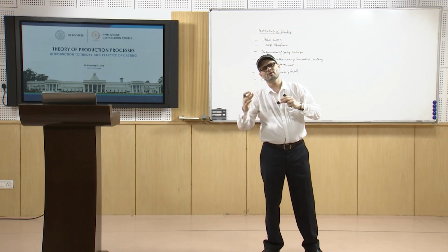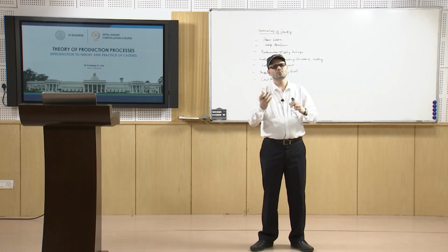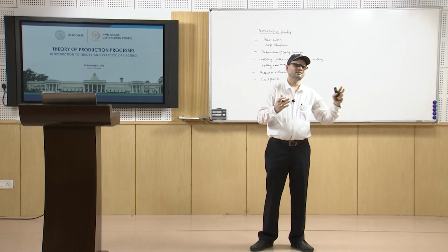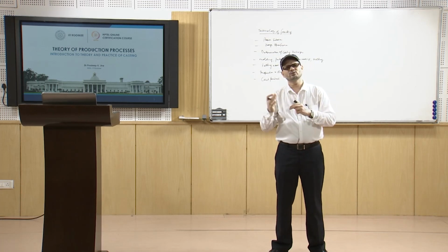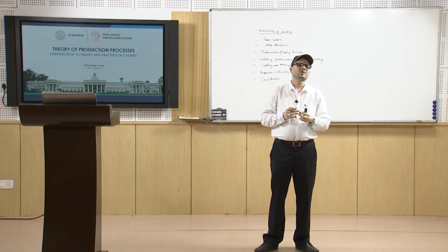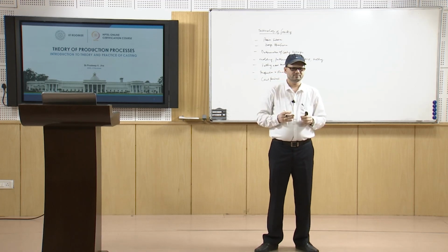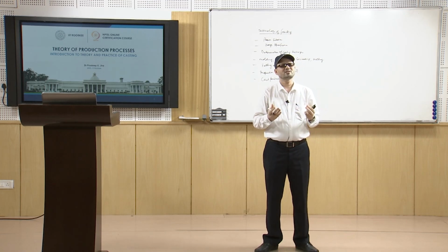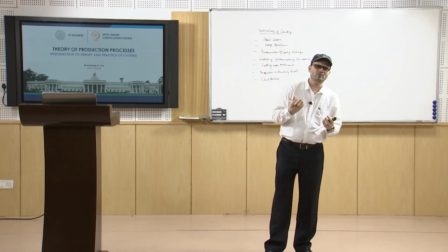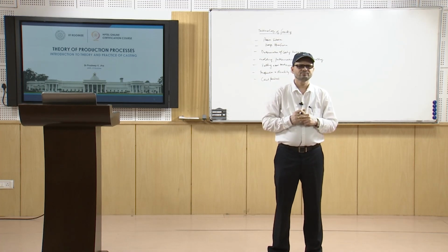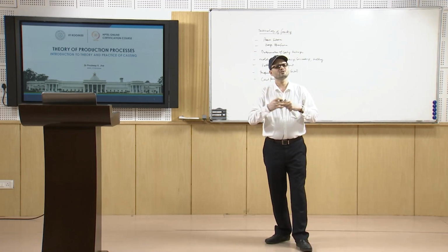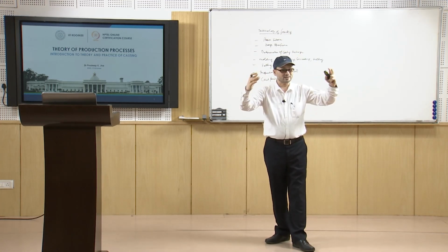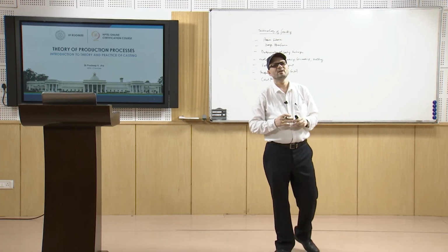You may think of going for die casting, where you use the metallic mold, or you may go for sand casting, where you use sand as the molding material. Certainly when you go for die casting, the surface finish will be better as compared to sand casting. But if the requirement is such that you need the product at a lower cost, and you do not have to go for a very large number of units and the product size is larger, in those cases you go for the sand casting methods.